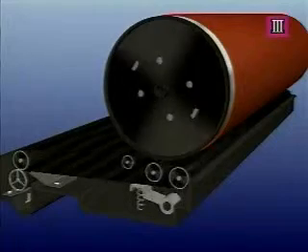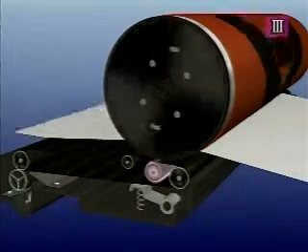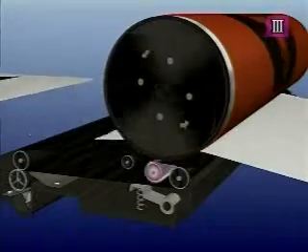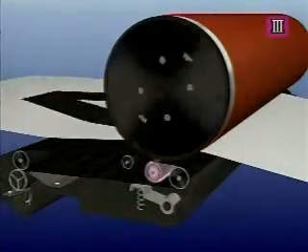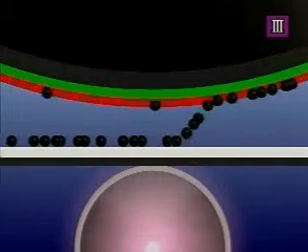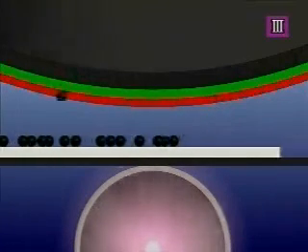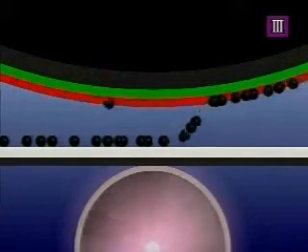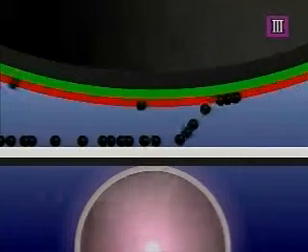Unlike the conventional corona transfer system, in the transfer belt system, transfer is performed with the paper adhering to the transfer belt completely. Thus, transfer efficiency is stabilized constantly, and a constant transfer output is applied between the leading edge and the trailing edge of the paper. In addition, if no paper is present in the transfer process, the power supply roller output is turned off to reduce the amount of ozone generated.